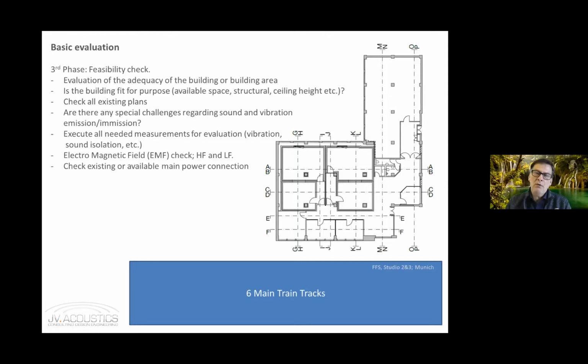So in other words, when the whole building is shaking with about 35 hertz, like in this example here, the whole system goes into resonance, and inside of these rooms, it's vibrating even more. And then you start hearing overtones and all that stuff. So it's not only about the problem with 35 or 40 or 50 hertz, it could be even worse.